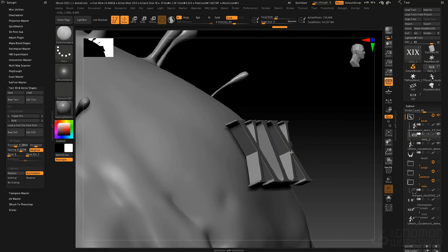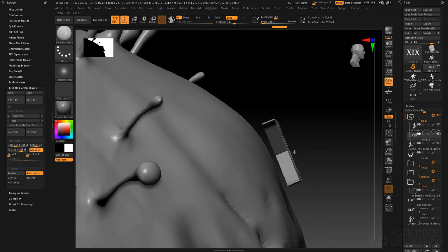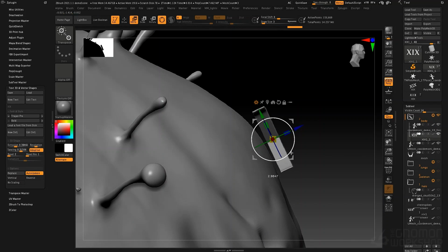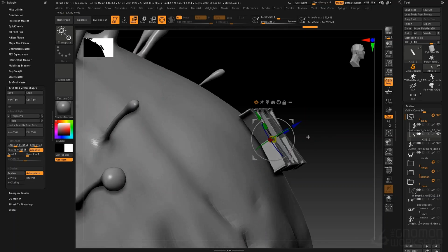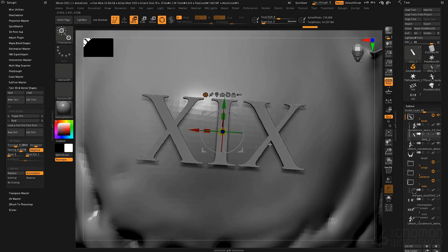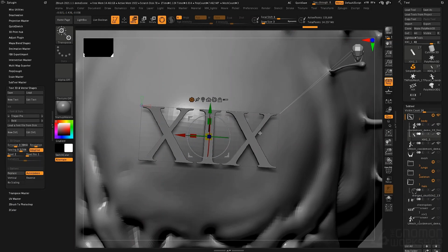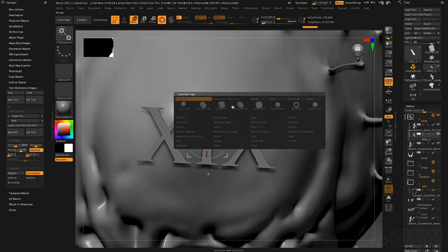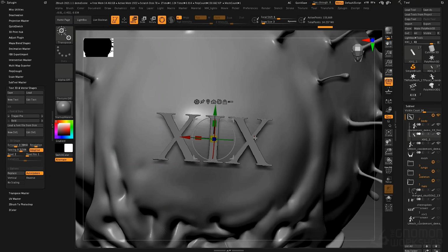Now I'm just going to reposition this, because in our undos, we actually undid some of that repositioning. So I'll go back to my gizmo by pressing W twice. Just snapping as close to a side view of this. This is easier to do, by the way, if you are actually at origin, but this character is posed, so it's a little bit trickier to get it lined up just right, but it's not at all impossible. So let's zoom this out a little bit. I'm going to hit the gear icon, and I'm going to accept that remesh so that handle doesn't keep coming up.